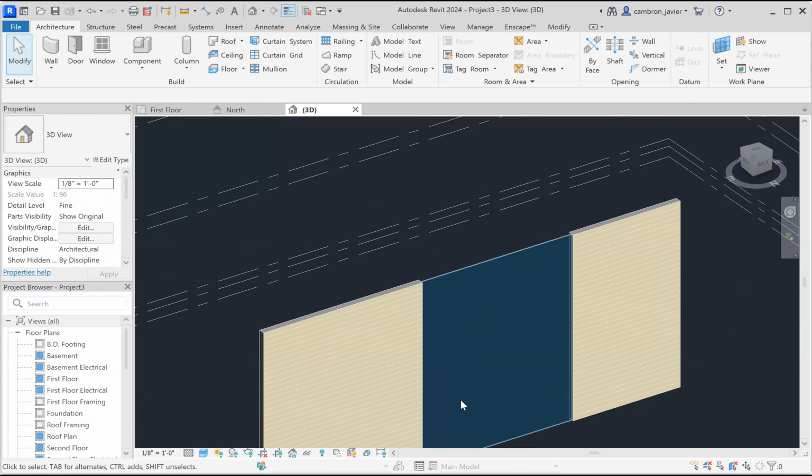And we could add that to the interior side, but it can get kind of tricky because typically you're going to have other walls and things on the interior side. So we want to jump to the elevation where we see the curtain glass too. So that's this elevation, which is my north elevation. Okay. And I'm going to change the detail level to shaded, and we'll set the detail level to fine.